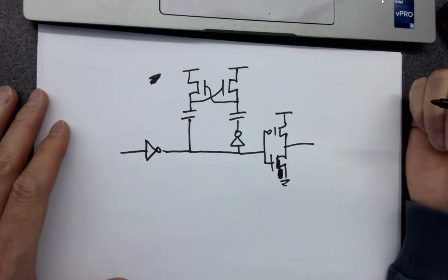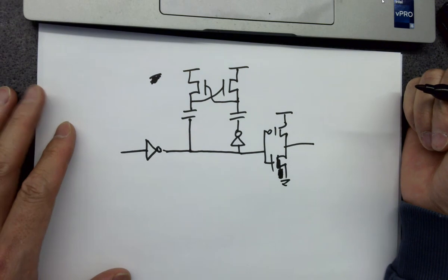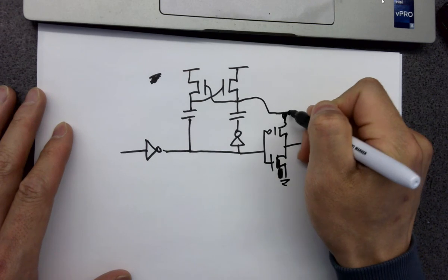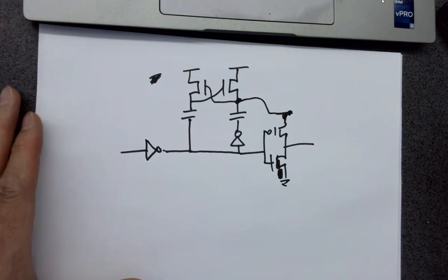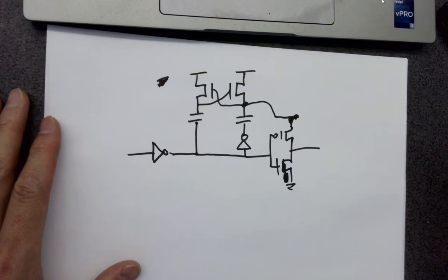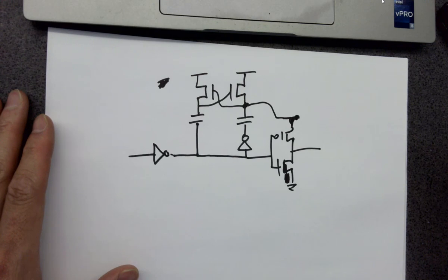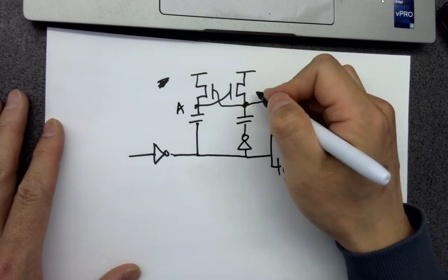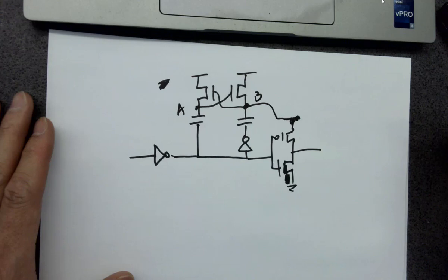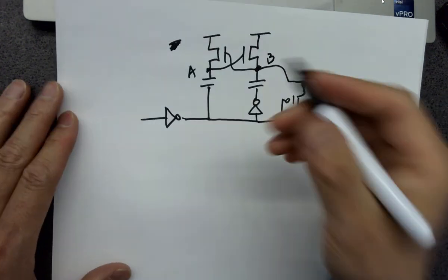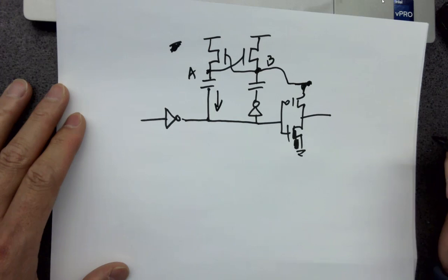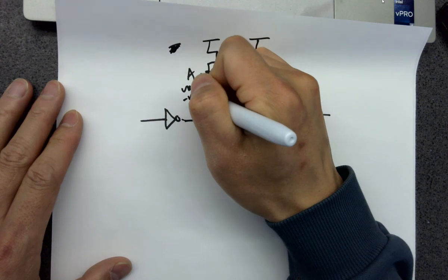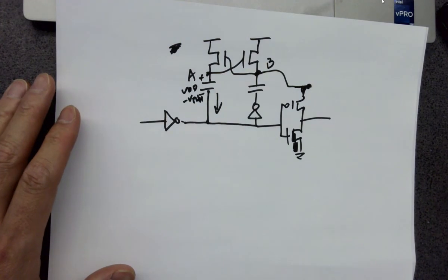So for a charge pump like this, all right, this one should be shorted to here. Okay. It's going to ask you what the voltage ranges are at this point, A, and at this point, B and Y. So at the very first step, when this one pulls down to ground, it pulls down a VDD to this plate. Oh, VDD minus VTHN to this plate.